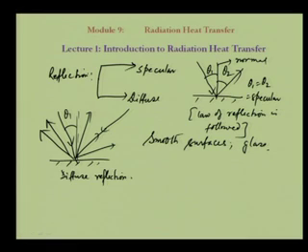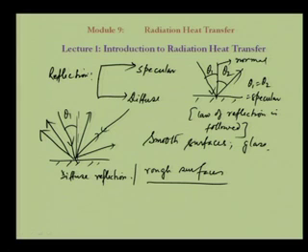So, it does not go by any particular direction, it can happen in any of the directions in this region of 180 degrees, 0 to 180 degrees, at any angle with the normal. Therefore, this is called diffuse reflection, and this does happen with rough surfaces. So, they do show this kind of behavior, and in practice, when we talk about radiation, it is basically diffuse radiation that is important, that is what we are going to discuss.